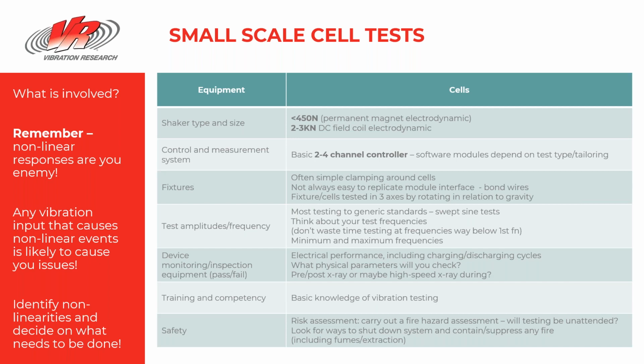Obviously, for device monitoring, you'll be looking at electrical performance, charge and discharge cycles, and what physical parameters you might want to check before and after, or do pre and post x-rays. I think there's even some work on high-speed x-ray imaging during vibration to see what's going on inside, but that's probably a very specialist task. From a vibration competency side, you just need basic knowledge of vibration testing to do cell level vibration testing. From a safety side, just standard risk assessments, and carry out a fire risk assessment.